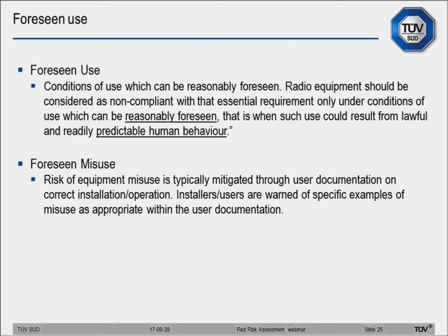What is foreseeable use and what is considered reasonable or predictable? What do you know about the product, its intended uses or environment that may lead to unintentional but predictable use? For example, is it possible that a smartphone may be dropped into a pool of water accidentally? If a smartphone was submerged underwater, how would this affect battery safety afterwards, for example? An outcome of this might be to ensure ingress protection sufficient to reduce the risk by safeguarding against a potentially dangerous fault condition during or after the device is unintentionally submerged in water.